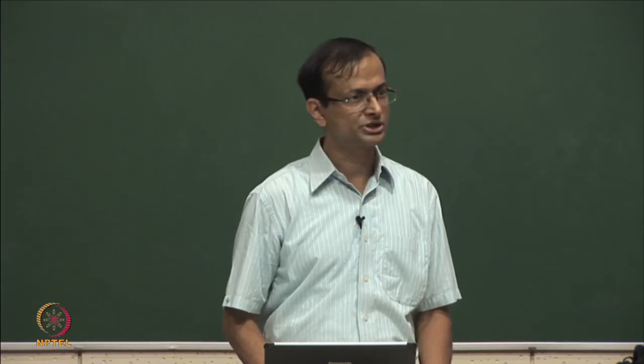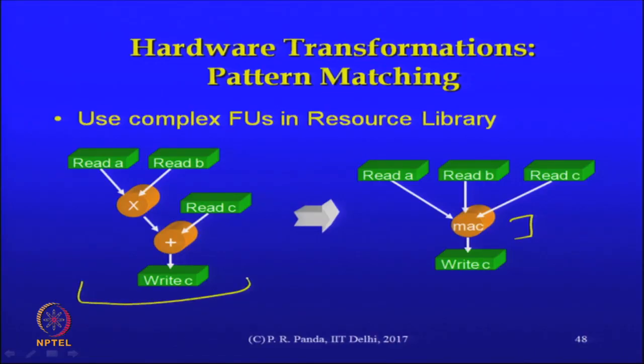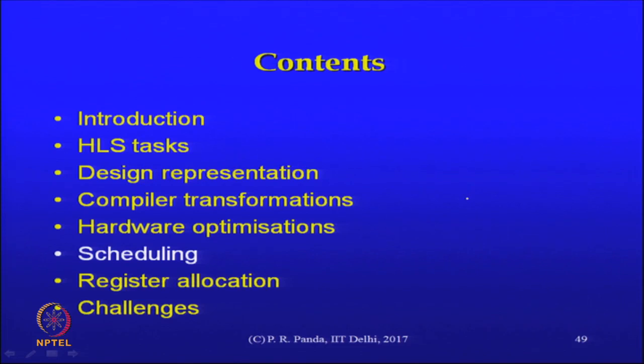Later on, if I do the scheduling on that graph, then it is hard to exploit the presence of that operator in any way, since they are individual operators: I have my multiplication, I have my adder. But early on it is an opportunity for me to replace a more complex subgraph by a single node, knowing the functionality of that more complex library operator. Those pre-processing steps being done, let us go ahead and discuss some of the core high level synthesis algorithms.